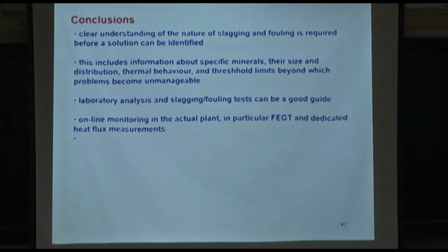No, it's because limestone is calcium carbonate, and as soon as it gets inside the fluidized bed, operated at say 850 or 900, or 800 degrees, limestone breaks down to calcium oxide and carbon dioxide. That's what happens in cement mills anyway. That calcium oxide comes from the calcium carbonate or limestone or even dolomite.